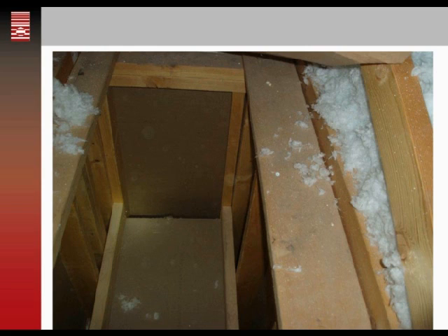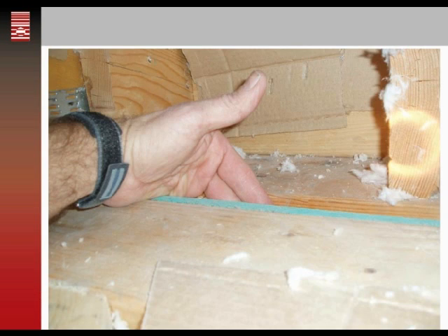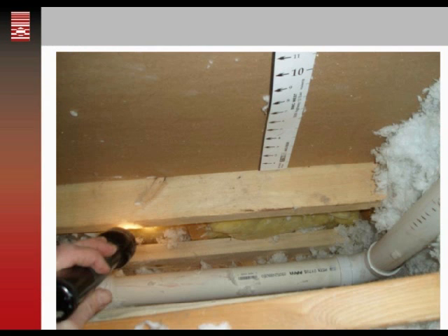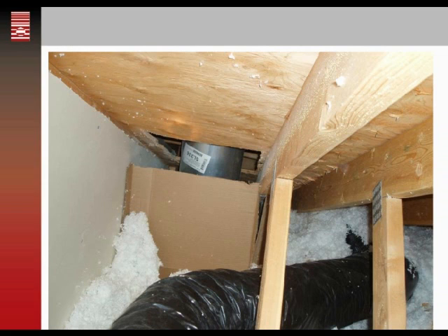The stack pressures on a house like this are going to be 5 or 6 pascals in the wintertime. So even if you have cardboard stapled over the top of this, it's not enough. You're still going to get quite a bit of air leakage through a bypass of this size. Some of the other bypasses, there were lots of them. Drop soffit details.